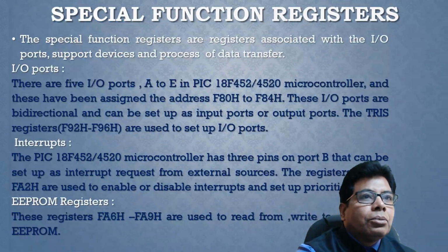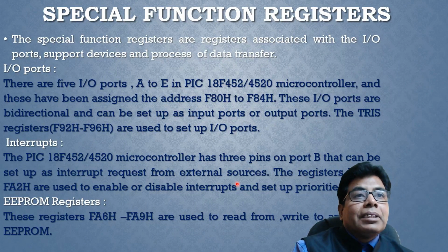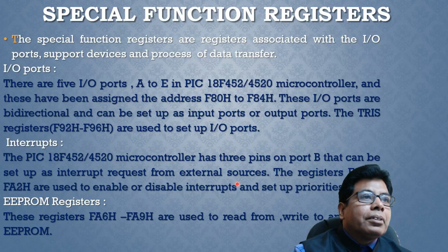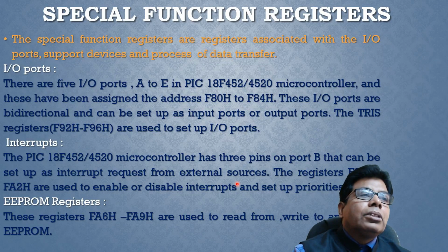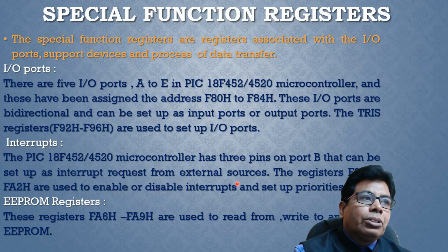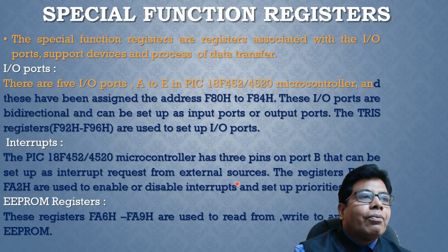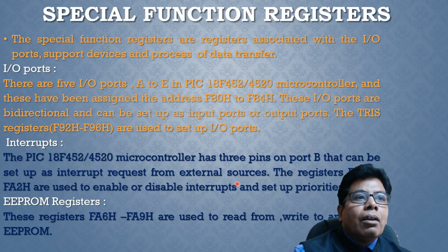Then let us go to the next. They are the functional registers. Special function registers. The special function registers are registers associated with I/O ports, support devices and processes of data transfer. Now first let us see the I/O ports. There are 5 I/O ports A to E in PIC